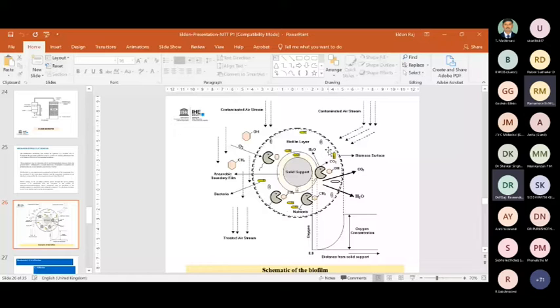Okay, the second mechanism is absorption. Because it contains a water phase, the pollutant gets into contact with the biofilm phase, it gets solubilized, and then it gets biodegraded. But again, if you have a hydrophobic volatile organic pollutant, then of course the solubility will be less, and that would lead to less removal of pollutant in the biofilm phase.